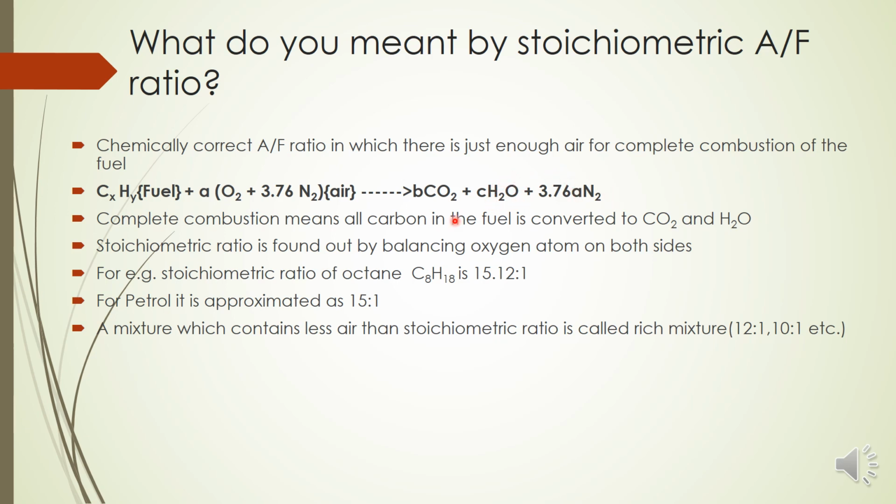And hydrogen and carbon can combine to form other hydrocarbons. So if it is a rich mixture, it will not be carbon dioxide and water alone. The products will have carbon monoxide, hydrogen, carbon, and hydrocarbons. So a large number of products are possible.